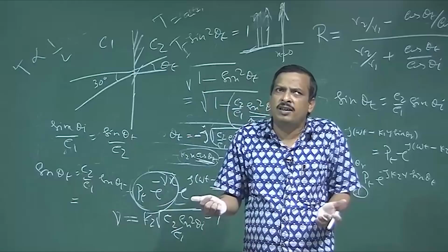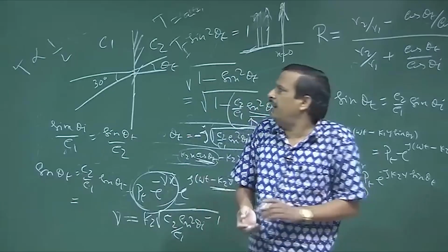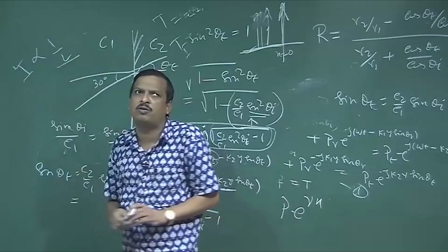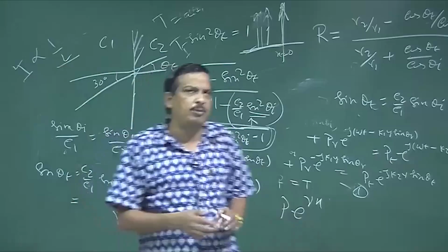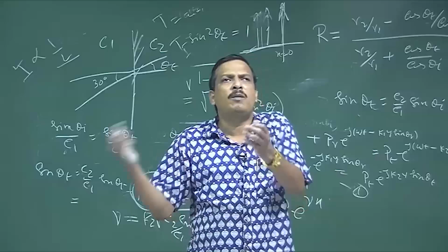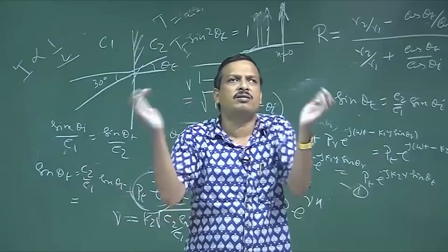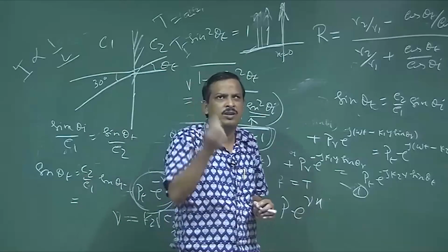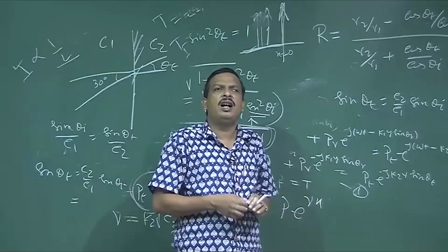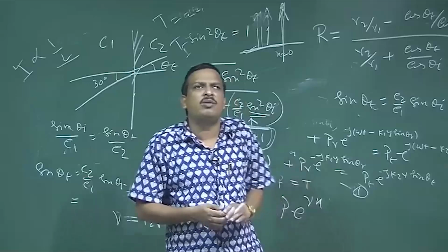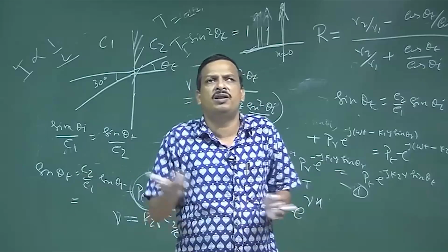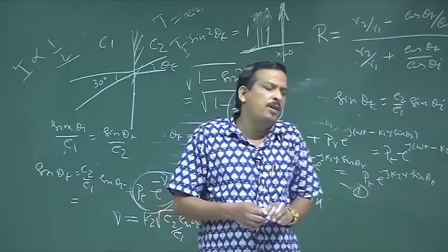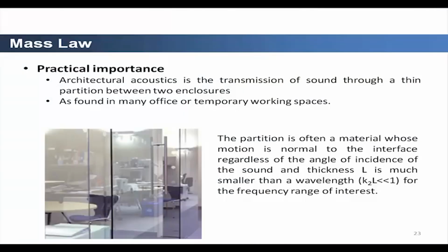This is contradictory. I said the transmission coefficient depends inversely on length, but in a factory there is a lot of machinery on the floor, and there is an enclosure made of a glass partition or gypsum board partition, and inside that partition the machine noise is drastically reduced. How does it do that? That is called the mass law, a physical property.